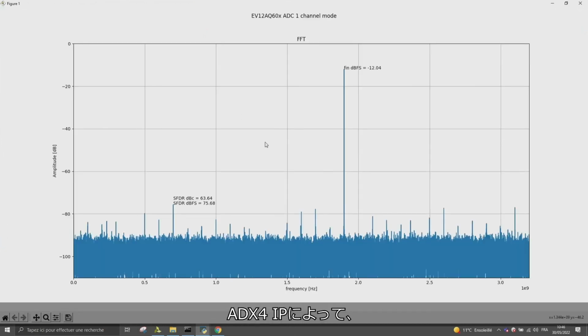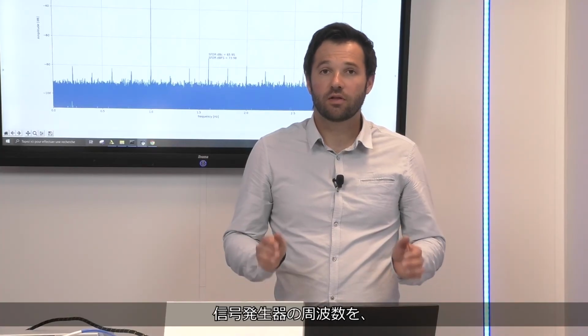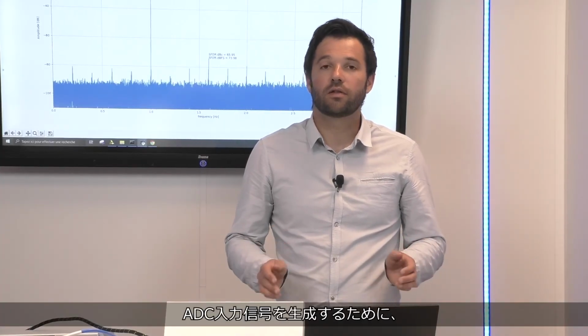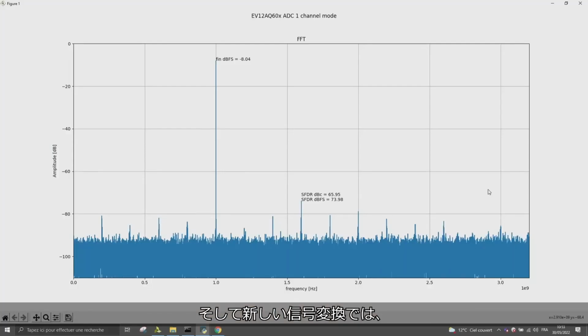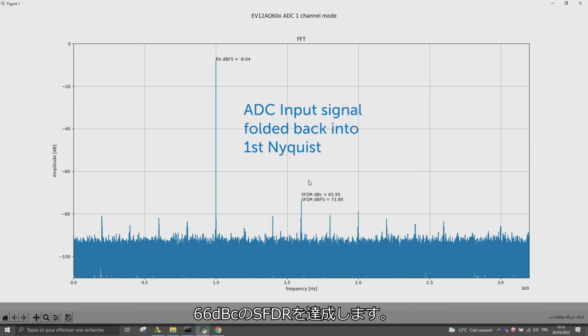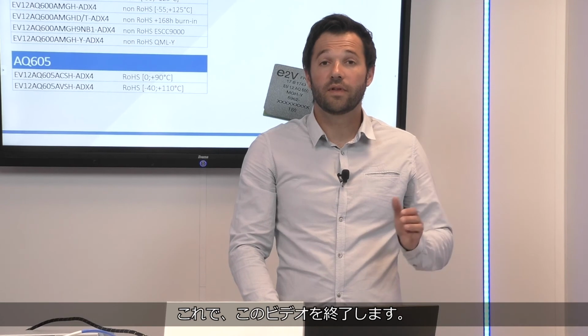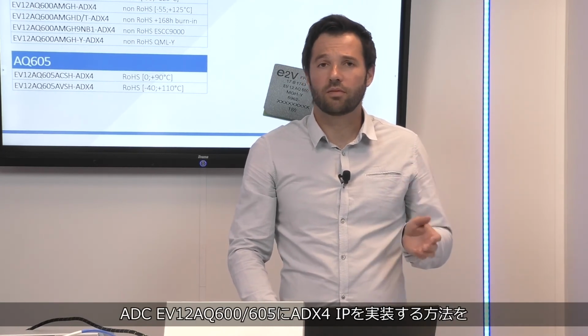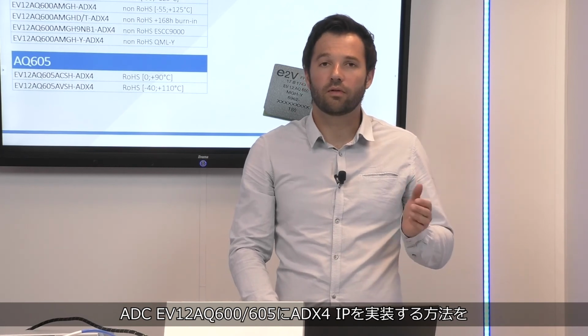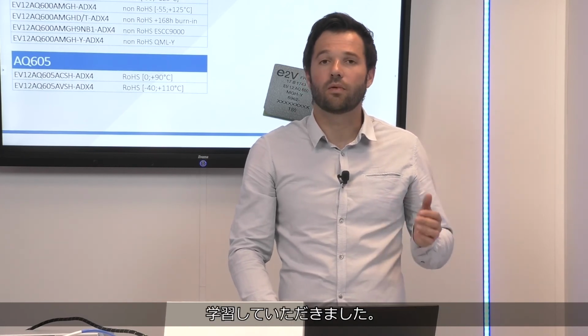So, with ADX4 IP, we can get an SFDR of 63 dBc. I changed the signal generator frequency to generate an ADC input signal at 1 GHz, and after a new acquisition, I get an SFDR of 66 dBc. This brings us to the end of this video. You learned how to start with ADC EV12EQ600 or 605 and ADX4 IP.